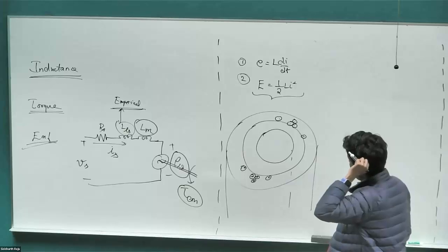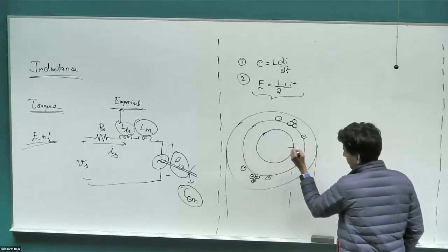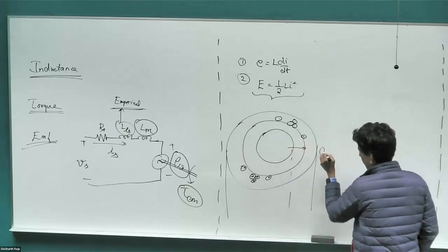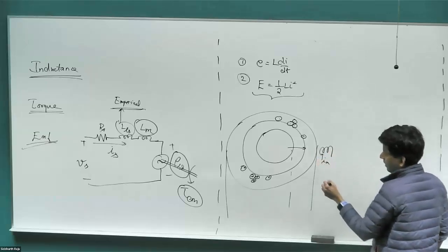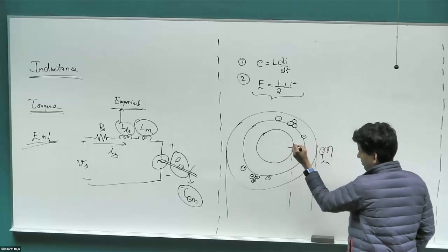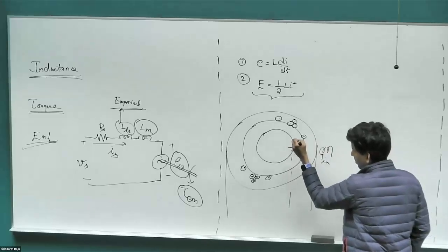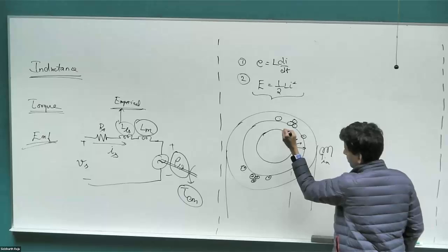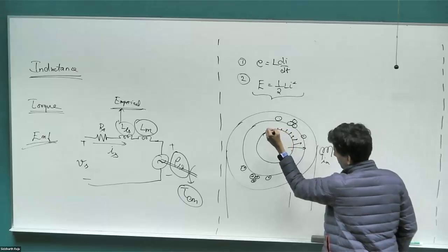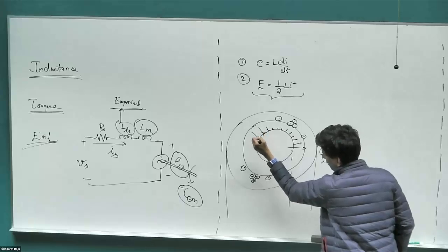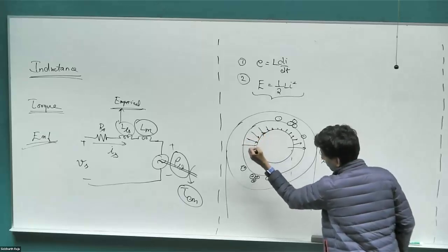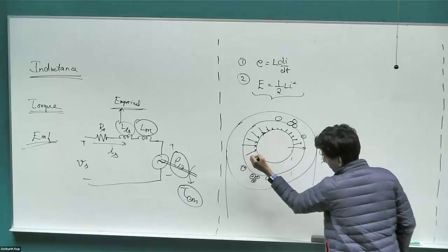So the B field in the air gap due to the A phase coil alone. We have the A phase coil, and we are pushing some current through it. So it's going to have a B field that's maximal along the A phase axis, and then something slightly lower as we go farther out. Again, all perpendicular to the iron at every single point, even though my drawing might not look like it at some points. With the peak along the 180-degree axis.